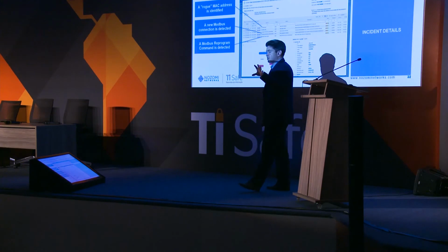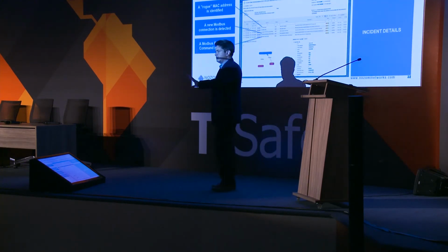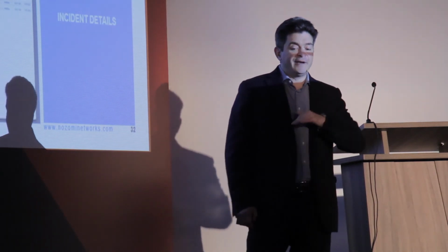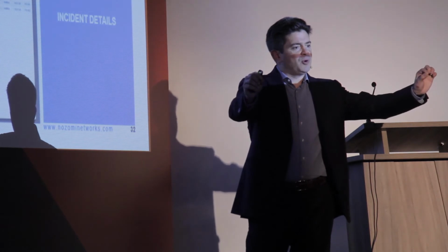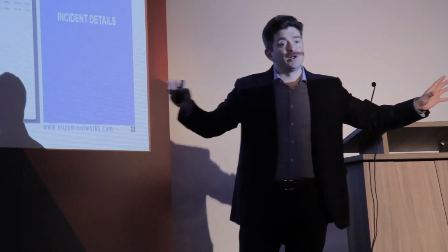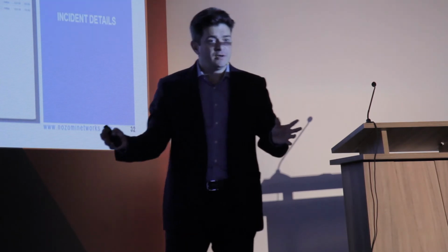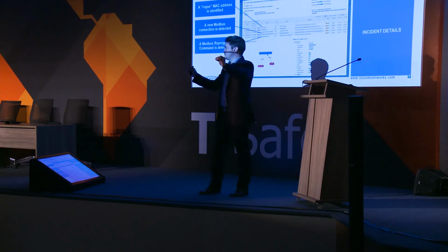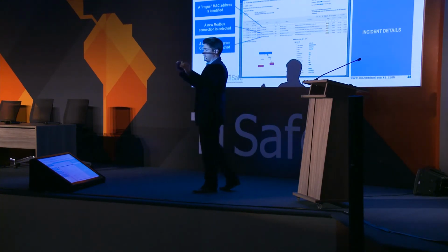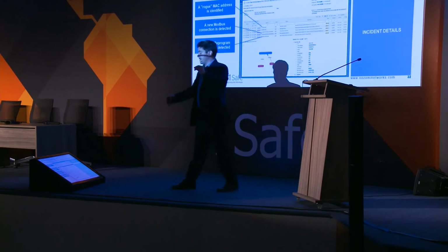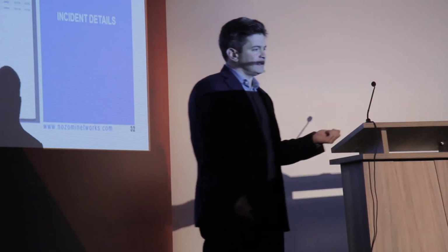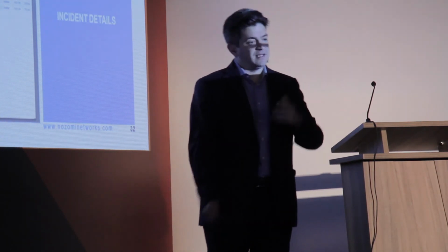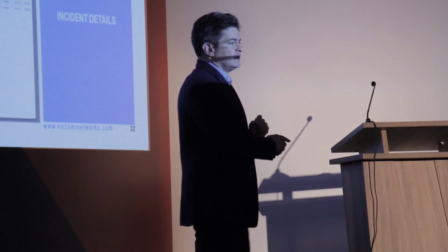So for example, the first alert was a rogue MAC address, right? That's a clear telltale sign of network spoofing. Somebody spoofing your network. Second one, a new connection between one node and another that was outside of the learning. So the learning phase has already concluded. We know how your process works. And these are two nodes that are not supposed to talk to each other, right? So we detected another alert that is now related to the first alert. And the next one is, well, it's using a protocol that is not expected, right? Malware doesn't really know what protocols you are using, so it tries to use generic protocols. And then they try to program your PLC, in this case, in a production run.